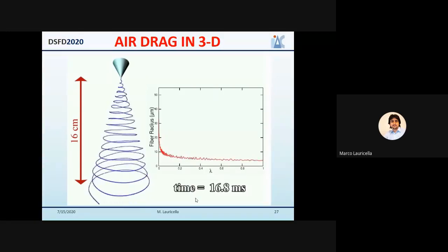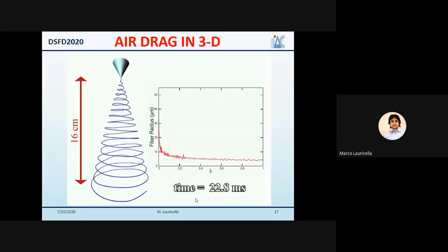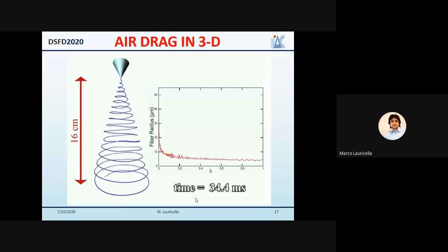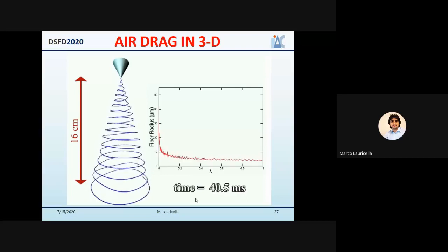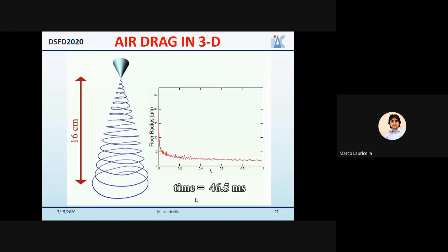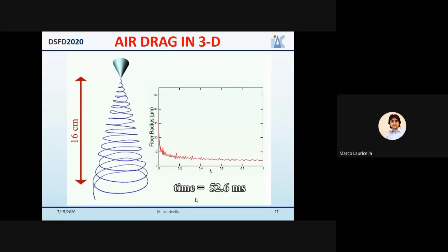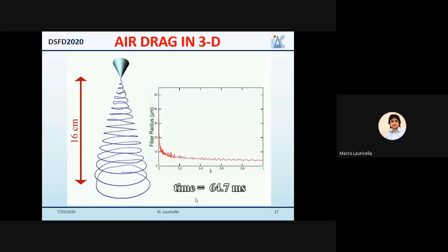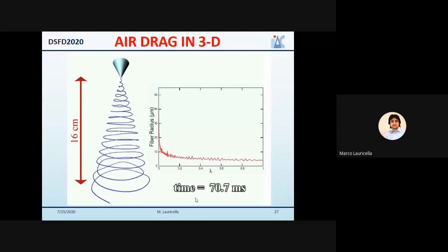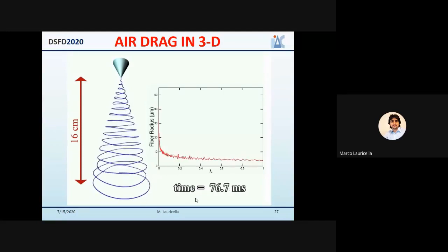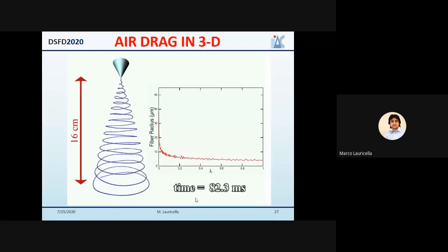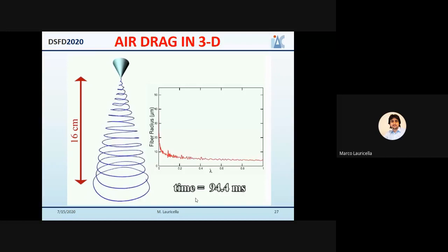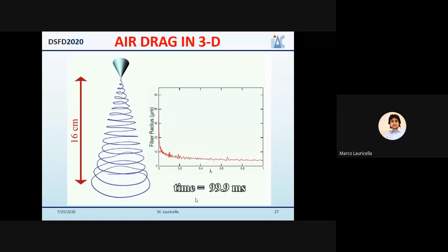Here is the process of a fluid with the parameters of a solution of polyvinylpyrrolidone. We can observe that the bending instabilities are well reproduced. Moreover, we can also monitor the fiber radius as a function of the curvilinear lambda parameter, which is on the right side of this slide. Here, lambda takes the value 0 if we are close to the nozzle, and 1 if we are at the collector. And it is particularly evident that the fiber radius decreases along the stretching path.